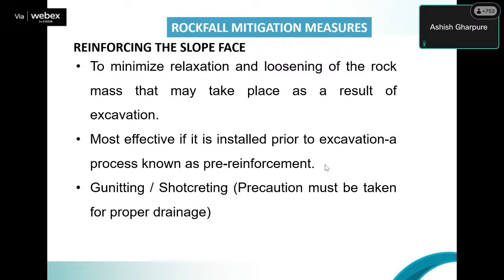So reinforcing the slope face, similar to shotcreting and gunniting, is one way of doing it. And there are ways that you can actually put anchors first and then do the scaling also, in order that the failure does not occur. So various practical measures can be adopted.